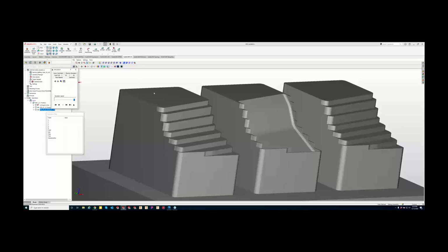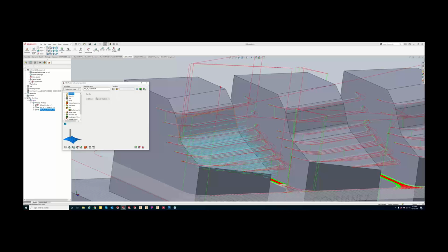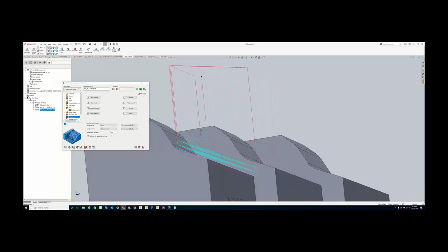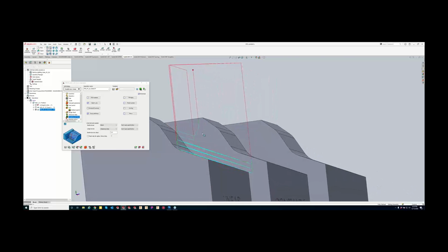That's in there. So now, if we go back into this operation, we'll go to our roughing and more. Depth cuts are set up there. I think if you just toggle the tool path for the iMachining, you'll be able to see what it's doing now. So now we can see, even though I told it that I wanted to cut 10 passes in here, it eliminated it down to 3 passes here because it knew the material that was left over.